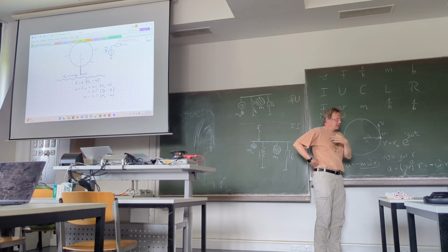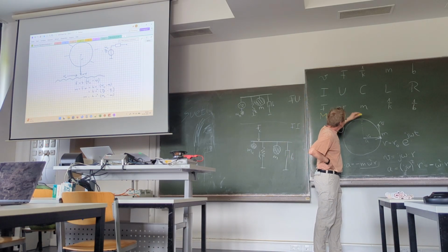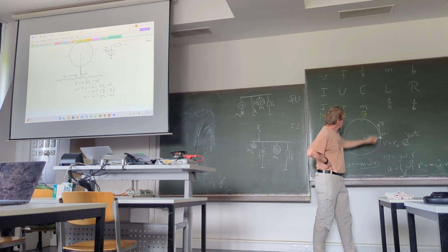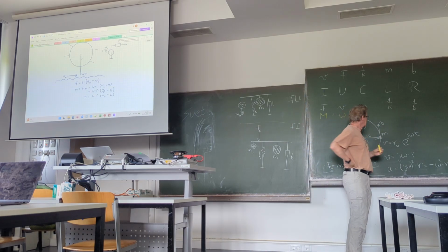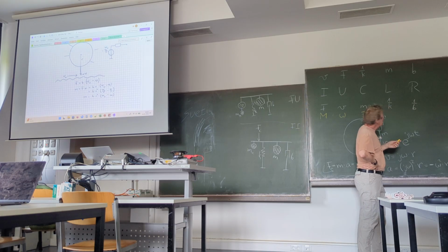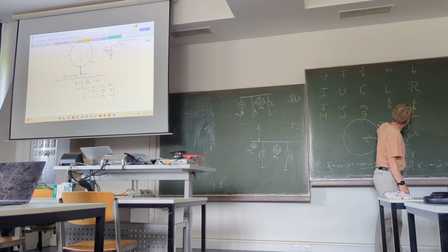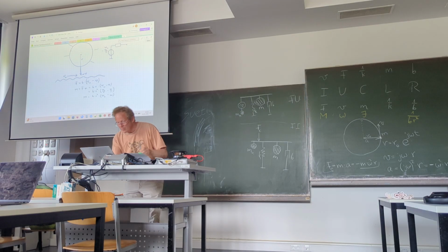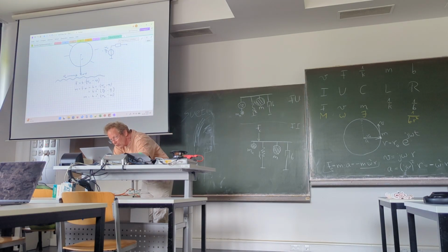Instead of a mass, let's add all the elements: we have the moment of inertia of the water wheel, J. Elasticity is not used here, but the resistance, the 1 over B, and the factor R squared. We see where it comes from. For rotational movements, this is what we call a beta.